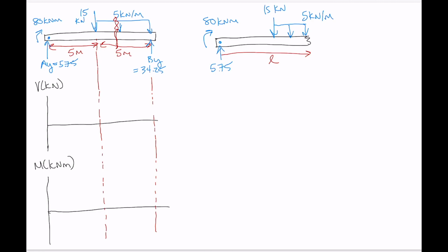And then we draw our internal forces, and again, just put them in the positive direction. So we've got internal shear that acts to rotate the section clockwise, and internal moment that acts to put the top of the beam in compression. Same deal: the sum of the forces in the y direction has to be equal to 0 for this little section cut that we've made.